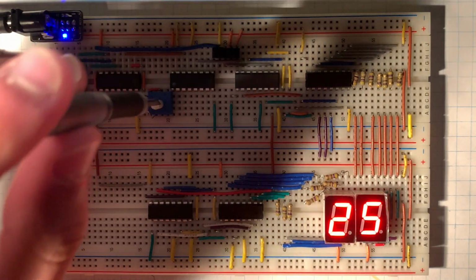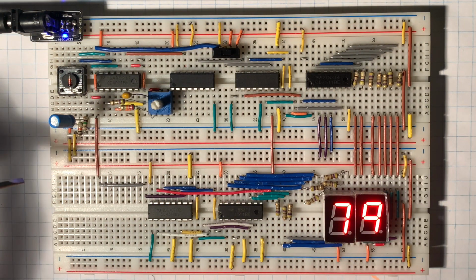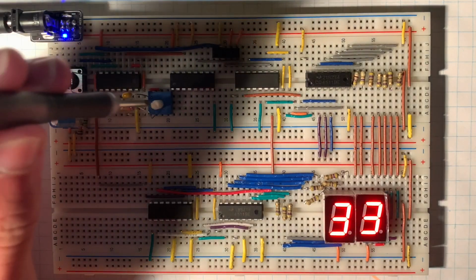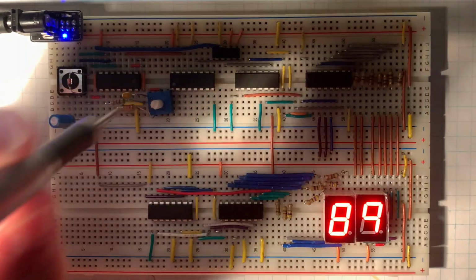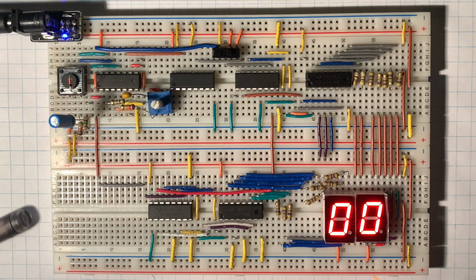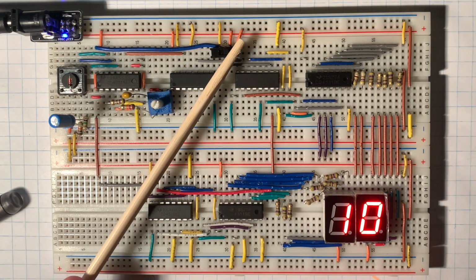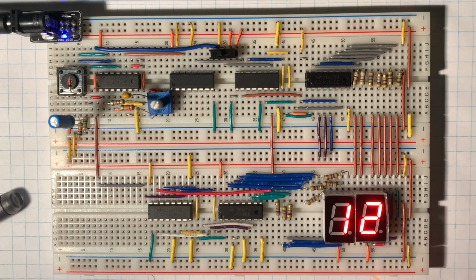The tens digit has to be 10 times slower than the first, so the carryout output of the 4510 chip for the ones digit is connected to the clock signal input of the 4510 chip for the tens digit. This build is able to adjust the frequency of the counting by using a potentiometer instead of a fixed resistor in the RC2 section of the NAND gate oscillator, which will be explained later in this video.